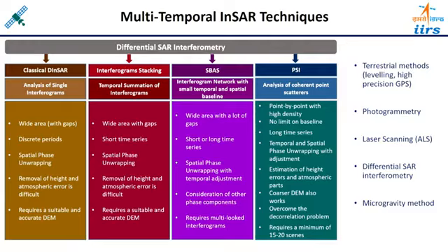So PSI and SBAS are called the advanced versions of the InSAR techniques. In fact, all of them are called multi-temporal InSAR techniques, but popularly, specifically SBAS and PSI are called the multi-temporal InSAR techniques. Nowadays people have started developing some more advanced techniques by combining the strengths of the individual multi-temporal InSAR techniques like SBAS and PSI. So in the current scenario, some hybrid InSAR techniques are also there in the literature, basically combining the role of SBAS and PSI techniques.